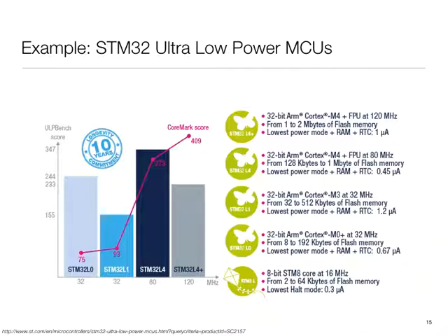Using virtual memory, anyone knows what virtual memory is, right? We basically give the illusion of a large address space and then back it up on the hard drive, on the storage. We can't do that here either, because even our virtual memory is pretty tiny. The storage is pretty tiny, a few megabytes of flash. So a lot of things that we are used to on a standard computer don't work out here.